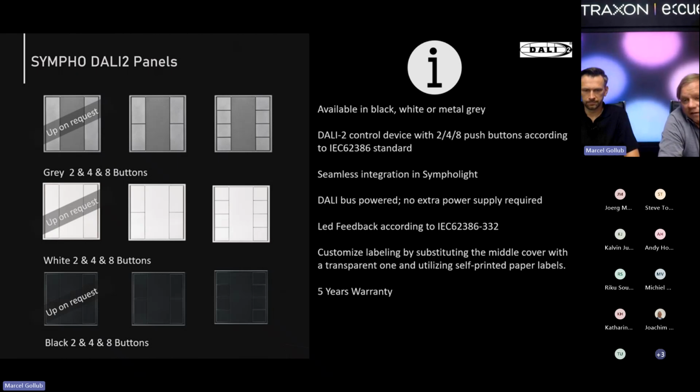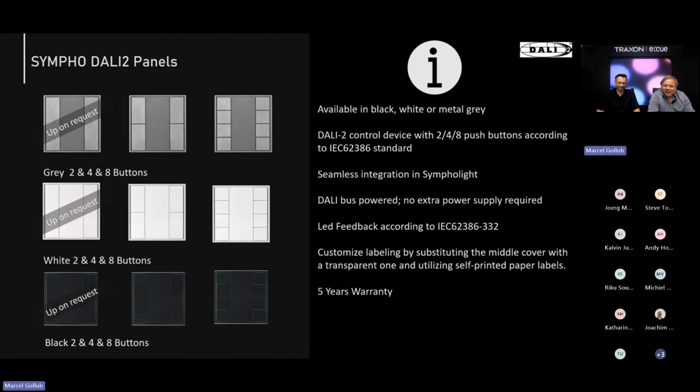They're all according to the IEC 62386 standard. As I mentioned already, due to the full implementation of DALI 2, they can be easily integrated into Sympholight. Of course, they can also be used with other control systems, but our recommendation is to use Sympholight. The nice thing about DALI 2 is that the devices are powered via DALI 2, so there's no additional power supply needed.